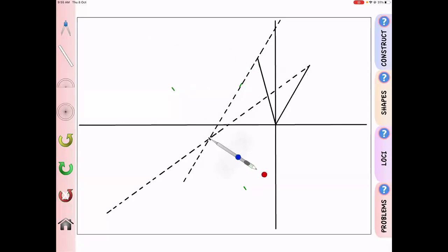And what should be the length? It should be 15.5. This is the problem, I cannot reduce it by more than this. Anyway, so you can understand that the crank, L2, is 15.5 millimeter. You can draw the circle of 15.5 millimeter. How did I get this distance? I just measured the distance between B1 and B2 and divided by 2. So that would be the radius of the crank. Okay,